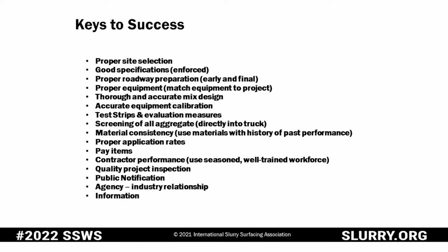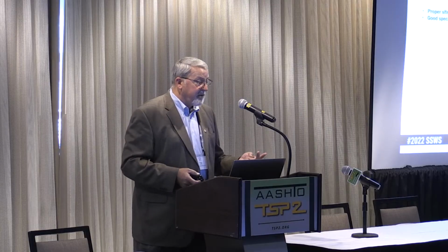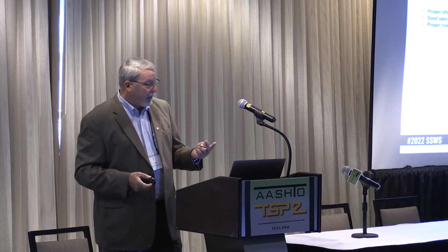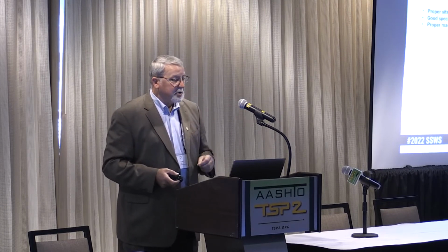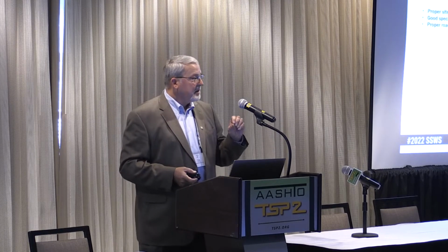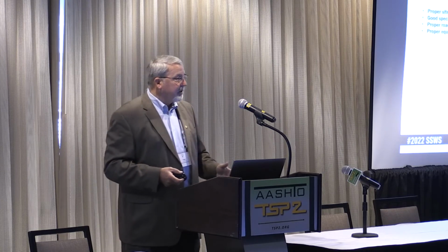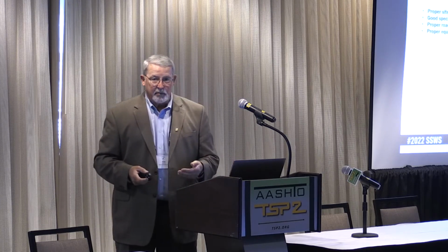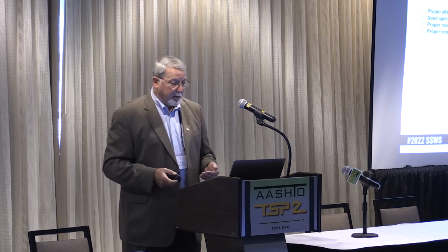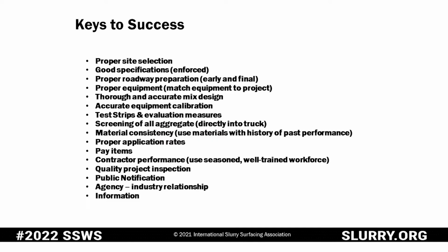Proper site selection, imperative. Good specifications, have to be enforced though. Proper roadway preparation, early and final. Get out and mark those patches, fix those curb and gutters, put those culverts in well in advance of the contractor coming in to do that work. Make sure you specify the right equipment for the type of job that you're going to perform. Thorough and accurate mix designs.